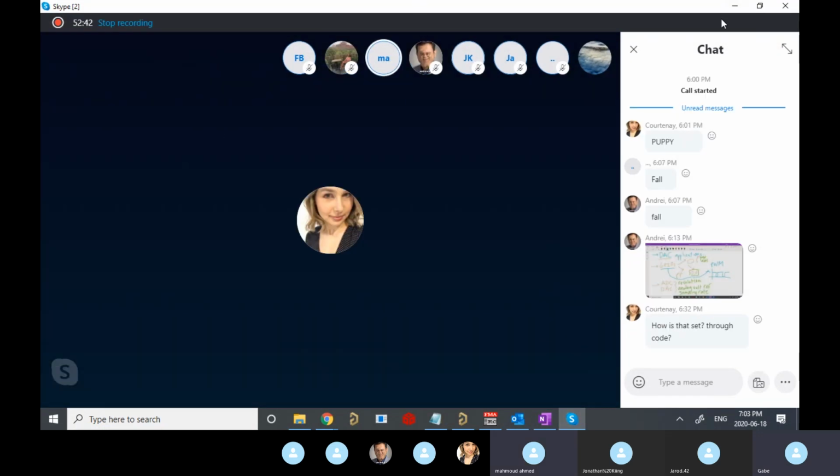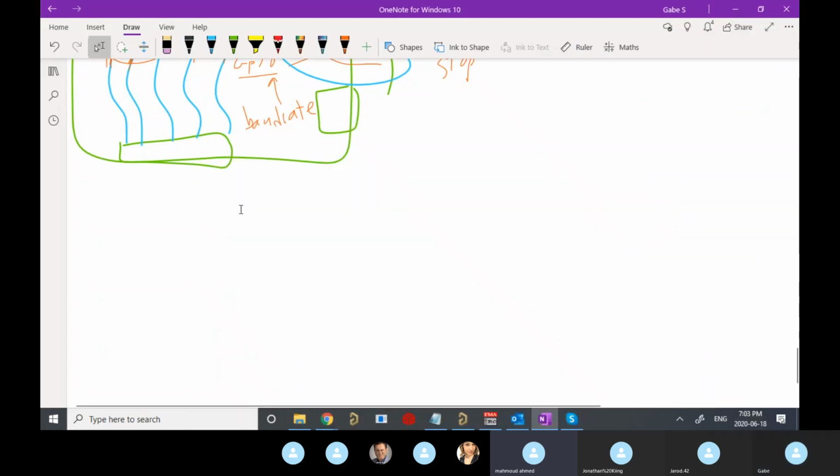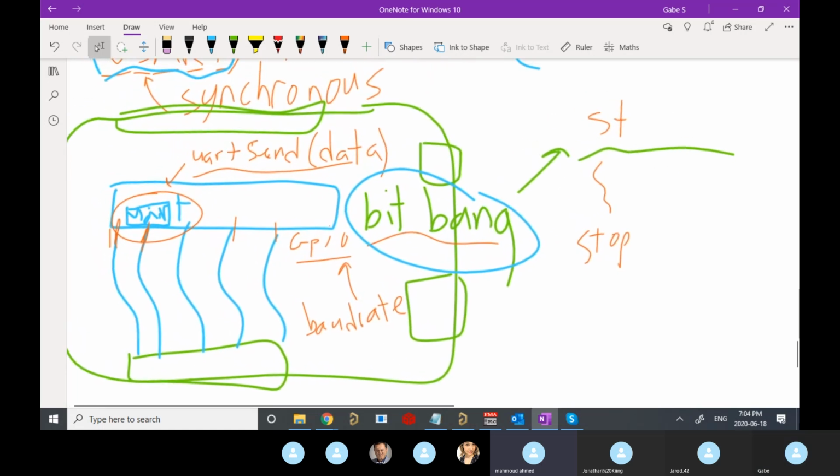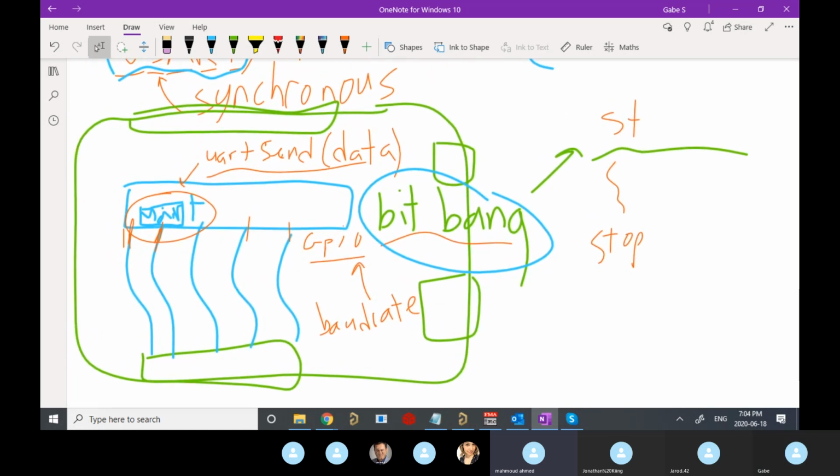One hour. Amazing. There is a major disadvantage to bit banging, just that you're not using special hardware for the specific UART or whatever, and so you don't have access to the interrupts and registers and all that stuff, and so it would take a lot more time from the operation of the microcontroller to do that, I think. Yeah, exactly. Yeah, I'd say so.